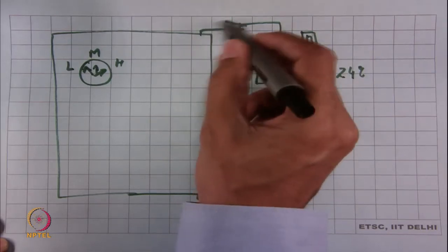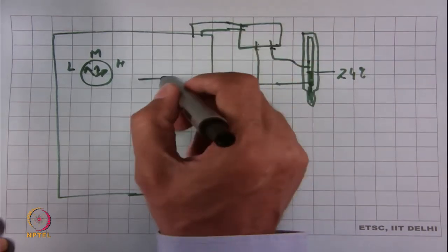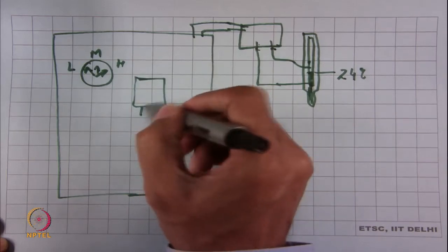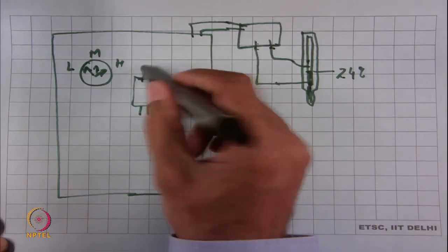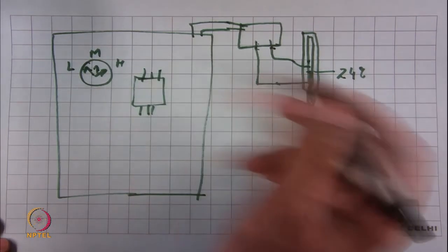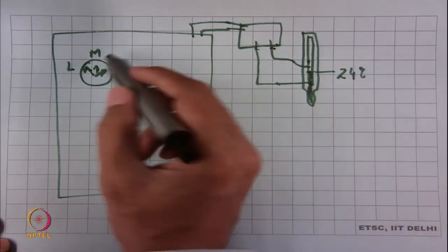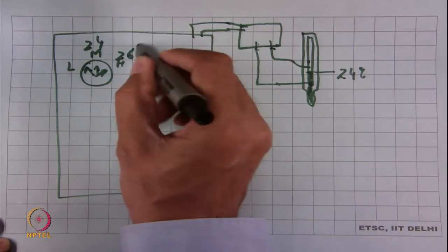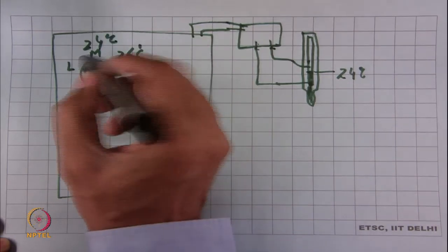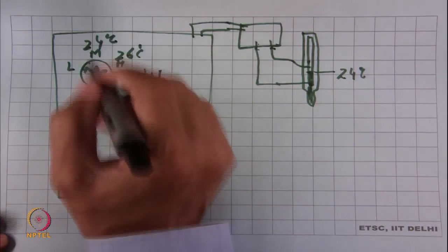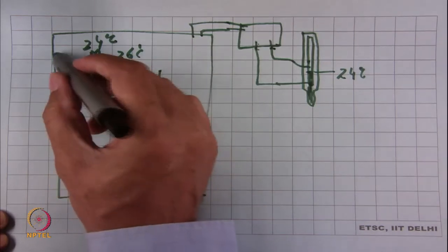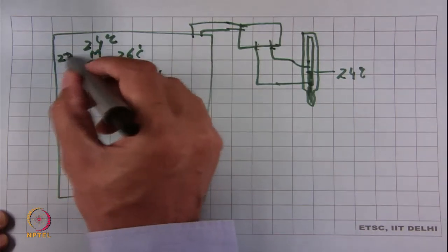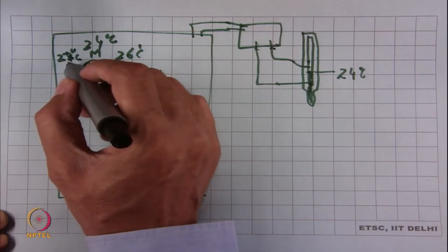So this comes into the control panel, and somewhere there is a 3-phase contactor that powers the compressor and the condenser fans. This becomes a way of controlling. The medium setting is 24 and the high setting is 26 for comfort, and then depending on the type of coach, it is either 24 on low or 22. In first AC they keep it at 22 degrees centigrade.